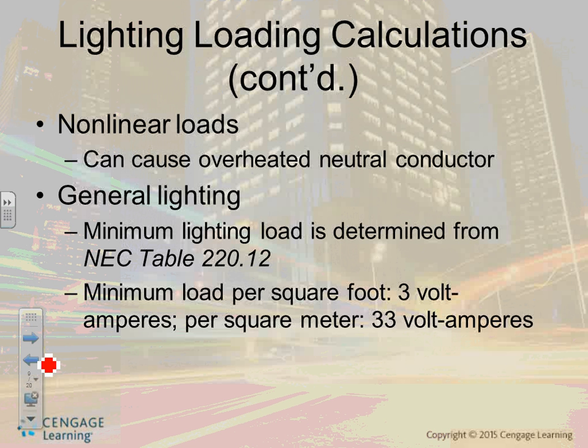For the LEDs, it takes the AC, typically the 120, and converts it into 24 volt DC and dumps it across these LEDs. That's why you need that driver for the LEDs. Now, for the fluorescent, what they do, guys, depending on the type, they take the 120 and convert it to different frequencies, and they fire these lights at certain frequencies. Long story short, they make them very efficient. That's the job of the ballast, to make the light work very efficiently.